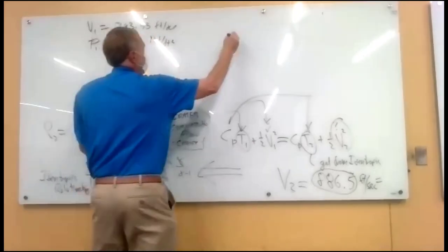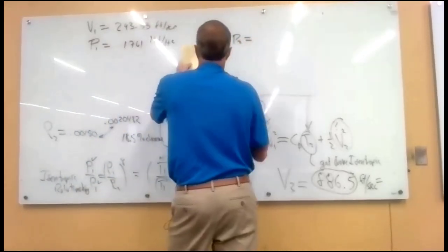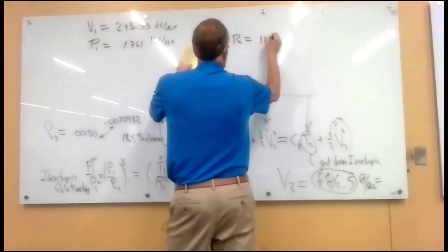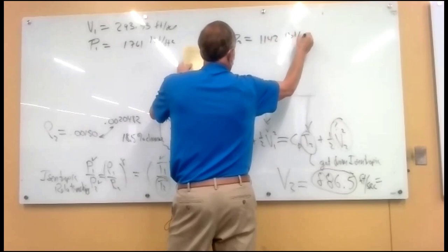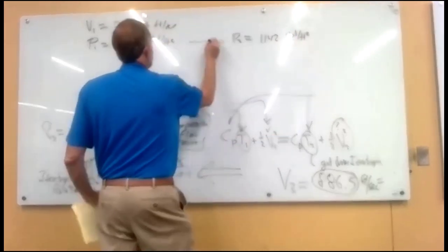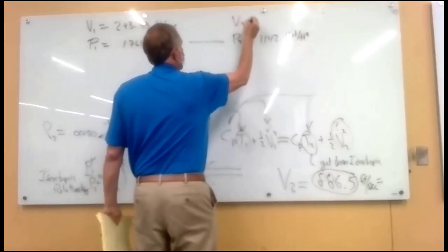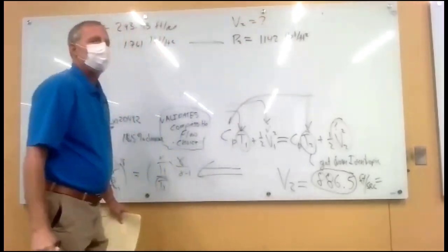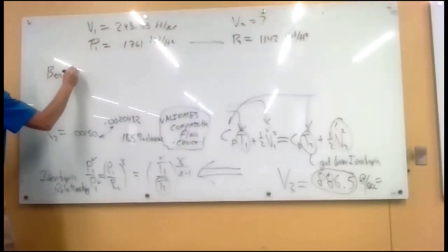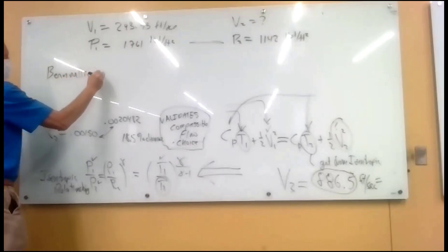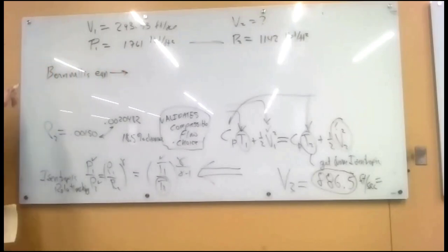And then I have P2 over here. That was pressure was measured. Right, so I know those two pressures, I know this, and I want velocity. It'd be real easy to just say, oh, I'm going to use Bernoulli's equation because it relates pressures and velocities, right? So I write that thing down.